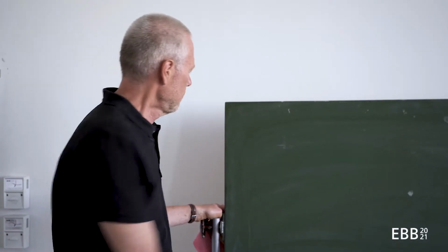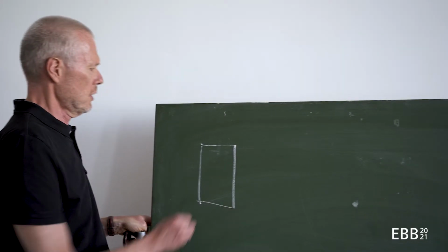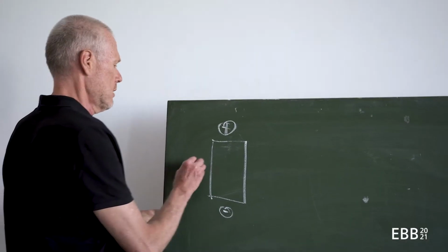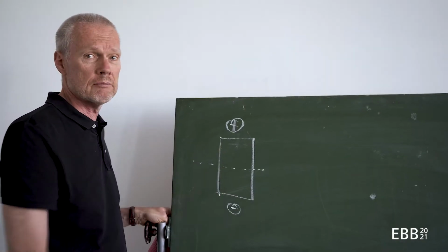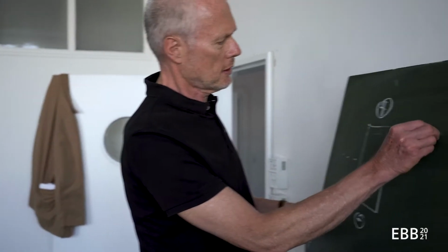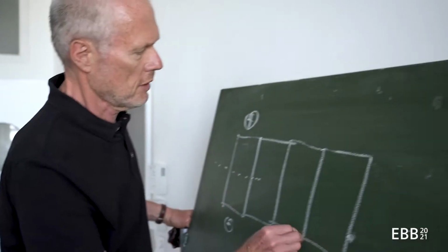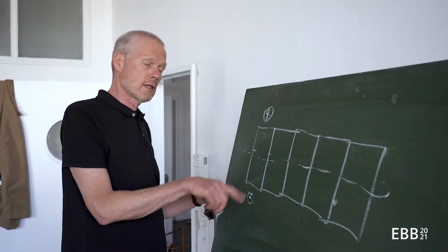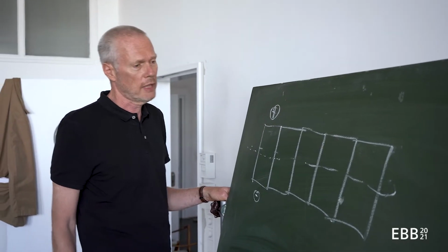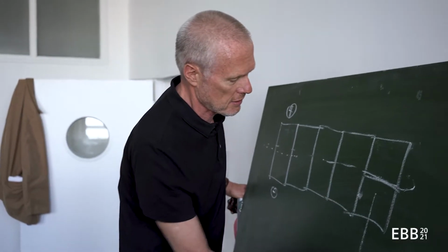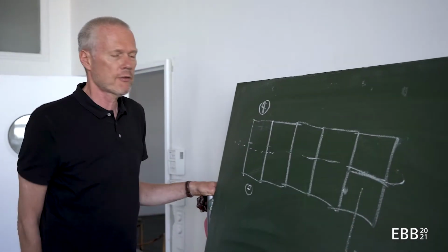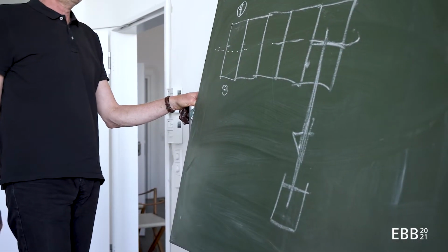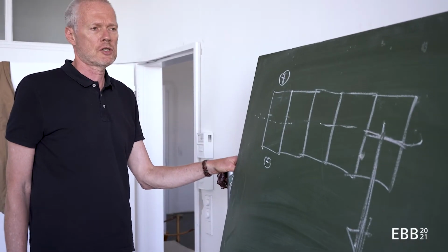We've been talking about beams before, and that inside the beam you would have the upper part being charged in compression and the lower part being charged in tension, and there's a neutral zone in the middle where this changes. So now I could go and put different beams one next to the other, and this would give me a sort of plate. But basically there would be compression in the upper part and tension in the lower. And I could also go ahead and cut the beam in half and put the section in a more favorable position, and then I would have to link these two by a sort of weave or diagonals, and this would be called a truss then.